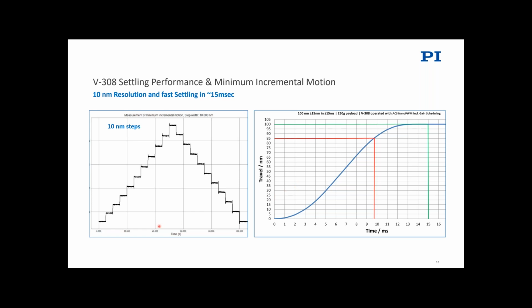Here's an example of some performance from this drive. So we can clearly make very well-defined 10 nanometer steps. So this is an example of a 100 nanometer step and settle with very fast rise times and settle times in the 10 to 15 milliseconds. So this is not quite as good as a piezo flexure, but really getting to be very good performance for this type of technology in